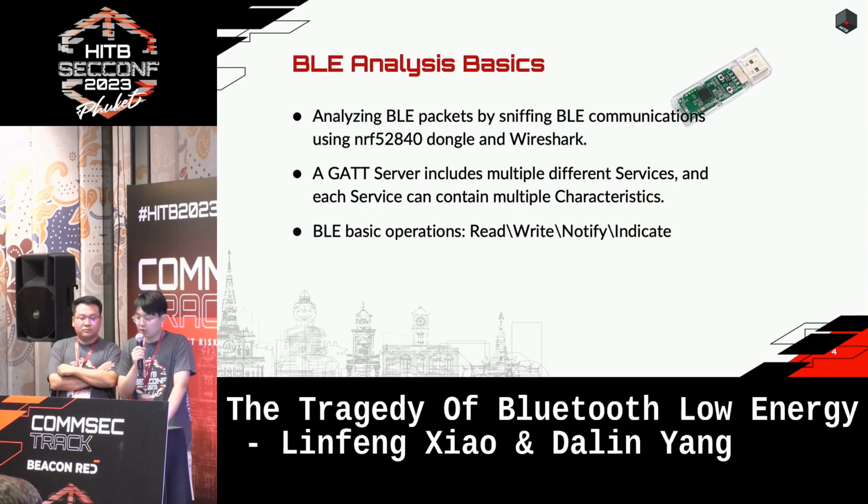Secondly, it's necessary to understand GATT, which is the basis for BLE application development. Generally, a GATT server has multiple services on it, and each service contains multiple characteristics. Usually, we directly operate on characteristics.